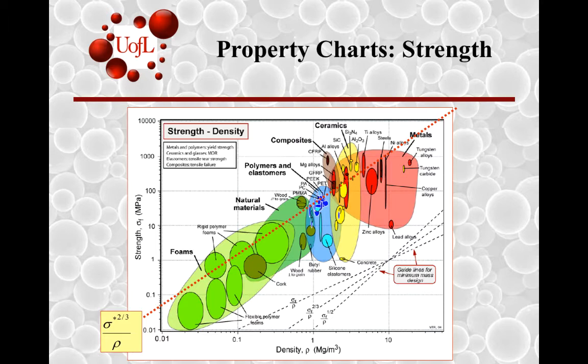Then we indicated that for a steel, for instance, one of the types of materials should be largely eliminated. If you go from a shape with a phi of 1 to a shape with a phi of 10, you could basically get a strength value that was now modified based on the material index.